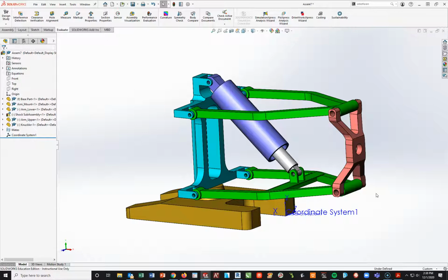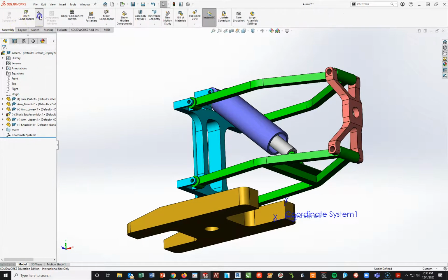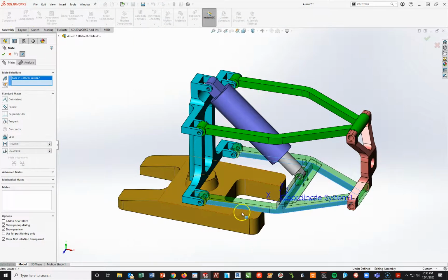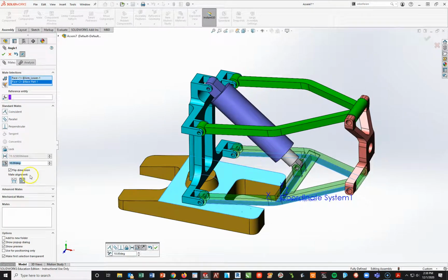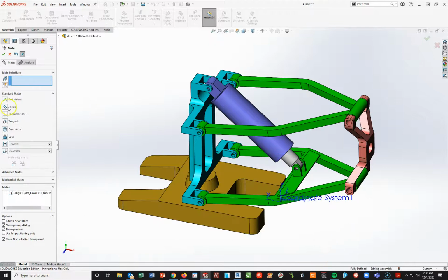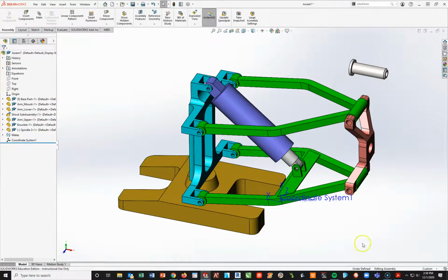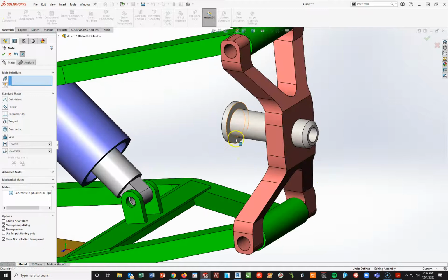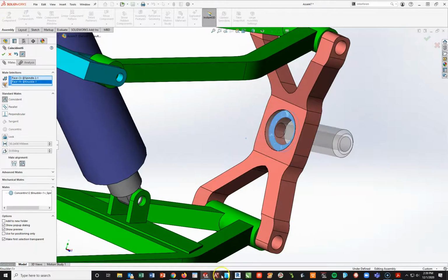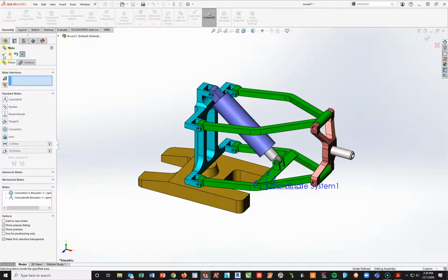We're going to add in an angle mate. It wants us to do a 10-degree angle mate in the assembly, between that bottom face there and this face here. We are going to do an angle mate of 10 degrees. Okay, check. Then we are going to close out that mate, bring in our spindle, and add in a concentric mate here. We're going to make this face right here coincident with that face right there. So there is my spindle as seen. Okay, close out my mate tool.